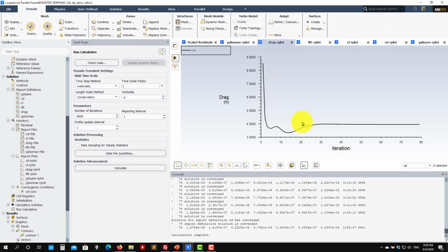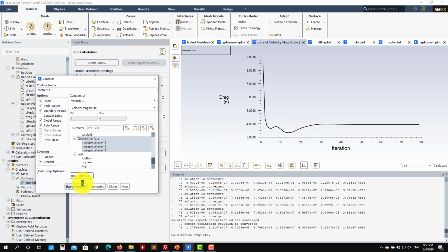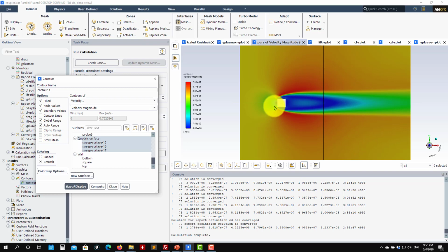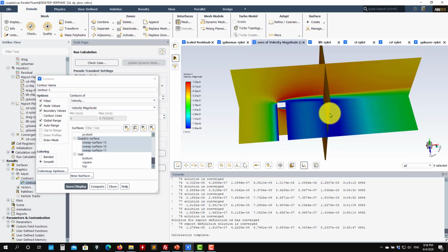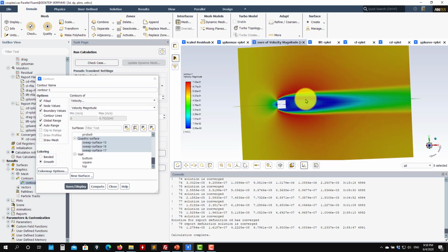So let's rerun the case, but now let's use the non-uniform solution. Before that, let's visualize a little bit the solution. See that this is the solution we have. I arrived at a converged solution, and what is interesting, look at what is happening here. Here we know that we have the onset of a wake, but the solver is just not predicting that. The coupled solver is arriving at this solution. This doesn't mean it is wrong, it is a solution.